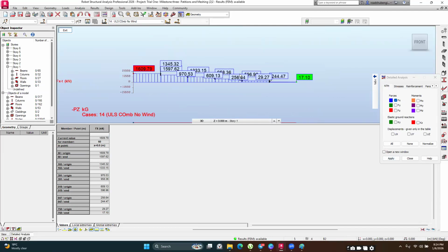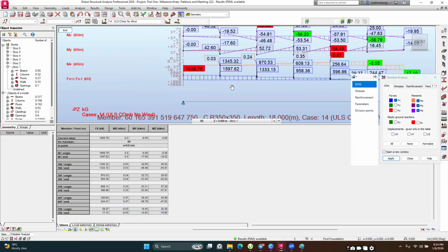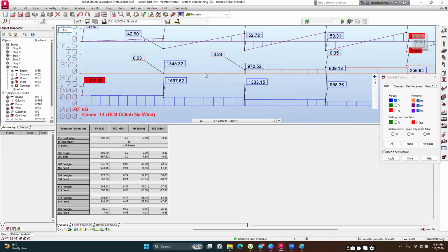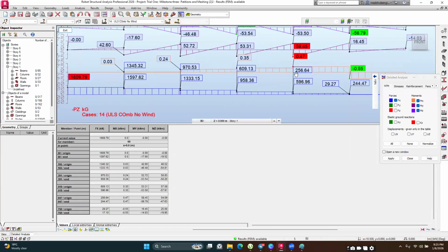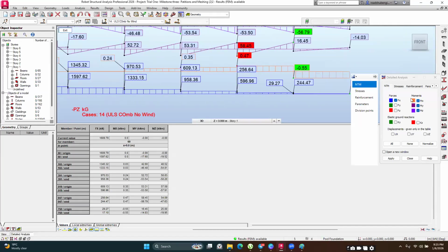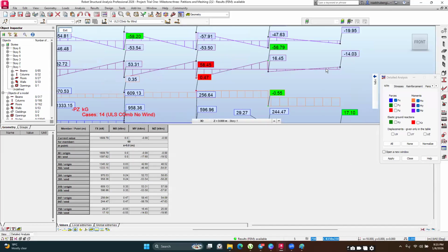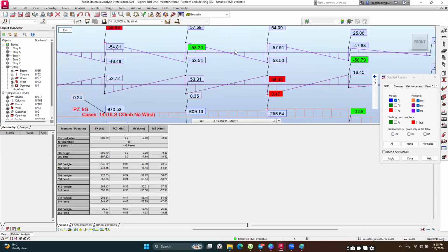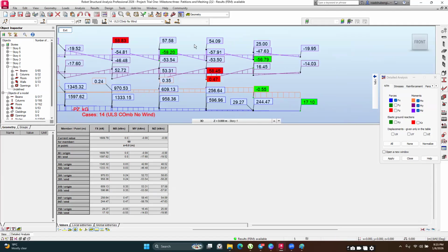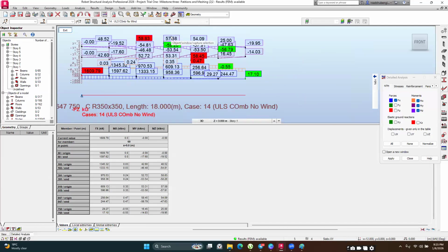So the axial loads are increasing. Then the other thing you may want to see are the moments. So just check all of them, and you can see them. So you can see the color. The orange here is the MX, that is the torsional moment. Then this color here coincides with MY. So these are the moments along the major axis. And then these are the moments along the weaker axis. So the detailed analysis enables you to have a better look or interact with your member more closely, or just understand it much better. Okay.